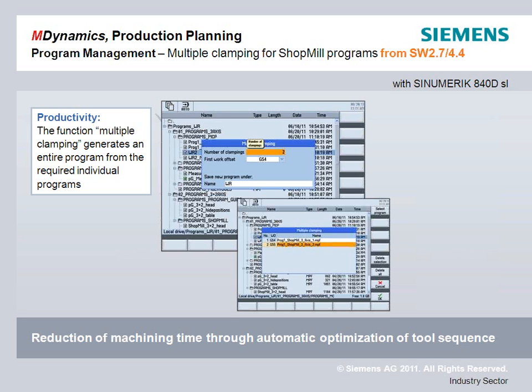You can say that my first vise has one work offset, the second vise has a second work offset, the third vise a third work offset. You identify the work offset for each program and say that I'm running 3 different part programs. The control can then take those 3 programs, look for the different tool change cycles within them, and say, all right, I need a number 10 center drill for these operations on my first part, for these on my second part, and for these on my third part. It'll do all the center drill operations without a tool change. Then it'll say, now I need to put in a drill out for tapping, and it'll work on all 3 parts at once. It takes these programs and condenses them together based on when the different tool changes are called.